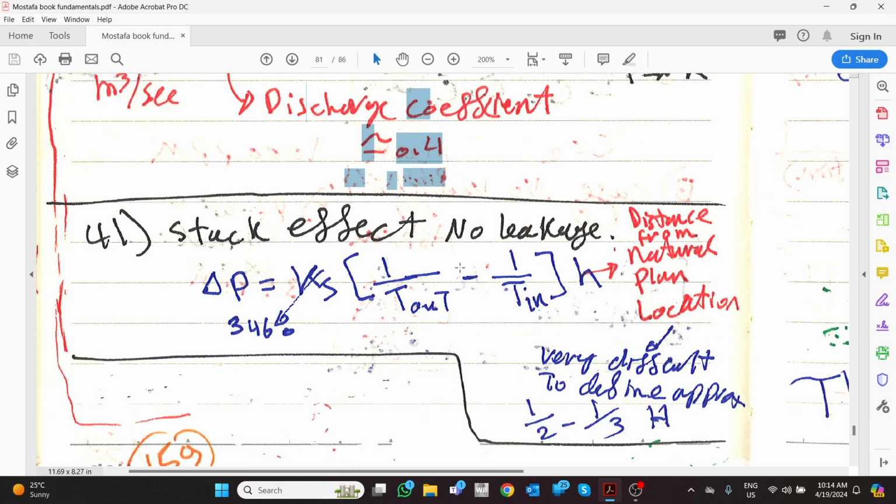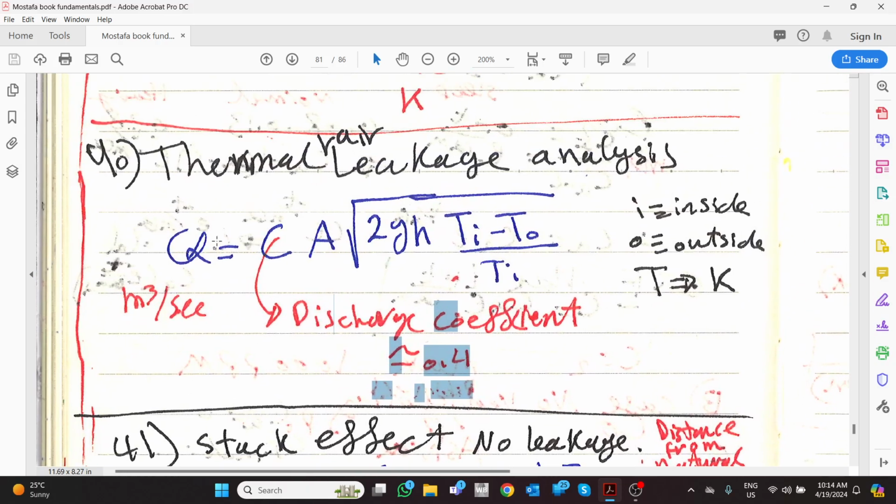And this application may be, for example, if you have hot smoke and you are opening a window for natural ventilation to the outside, it will use this to get a resultant. And by the way, it is a transient mode, which means that when too much hot smoke is accumulated, the temperature inside gets higher and higher, so the flow rate will be higher.